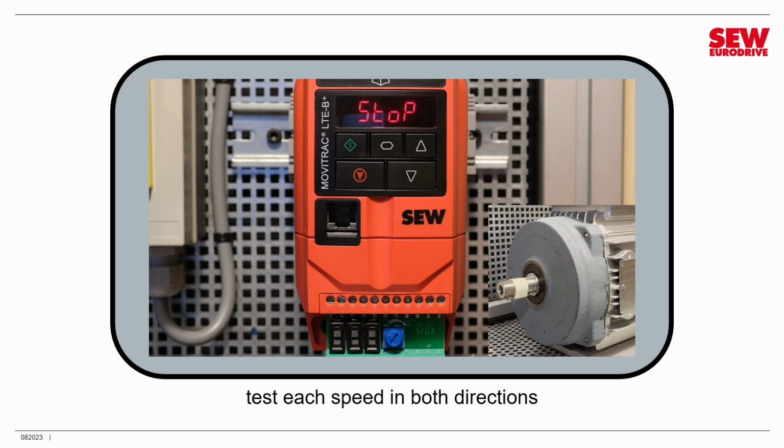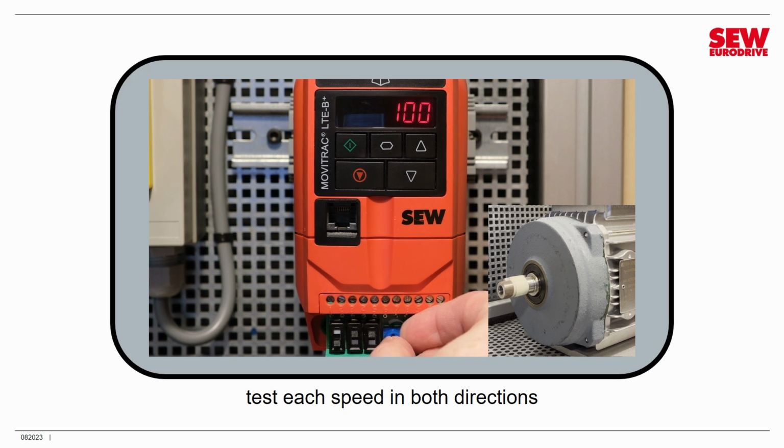I'm going to start by turning the switch connected to DI1 on. That should run in the clockwise direction. All right, we're running at 100 RPM. Now let's go to the next speed by turning DI3 on. That'll give me 250. All right, now we're going to turn the pot all the way up to give us that extra bit. And we have 500 RPM, and finally we'll go to 1000 by turning both switches on. Works fine. Bring it to a stop.